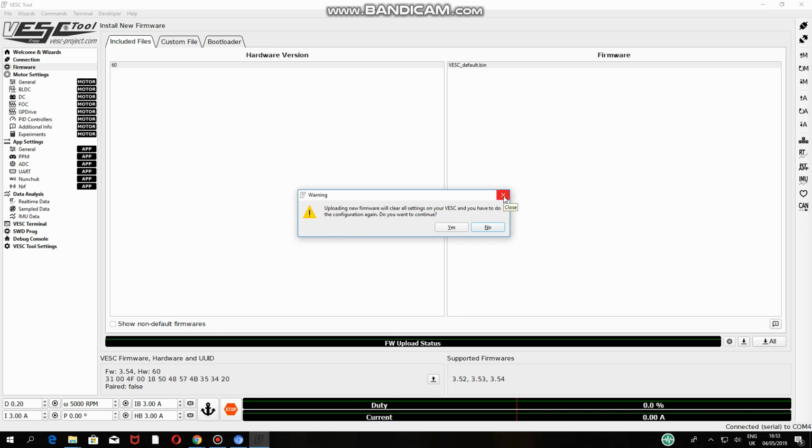You do that to Vesc number 1 or any Vesc, and then you do exactly the same to your second one. Even though they are dual, you still have 2 ports. So it's like 2 Vescs but in one body. So you have to update or upgrade both of them. If you just do one, if you carry on with setup of the board, when you get to almost final steps, you will be thrown right back because you did not upgrade them both.